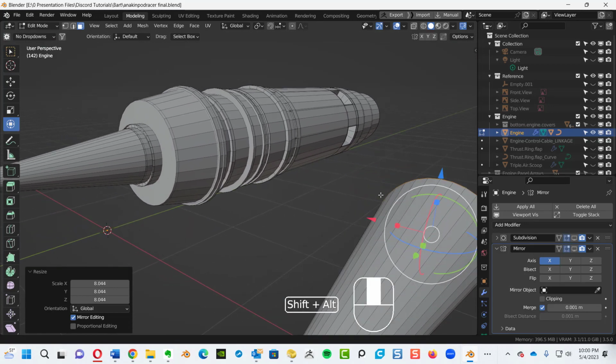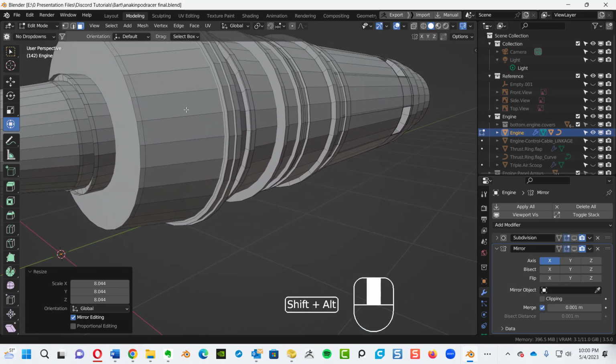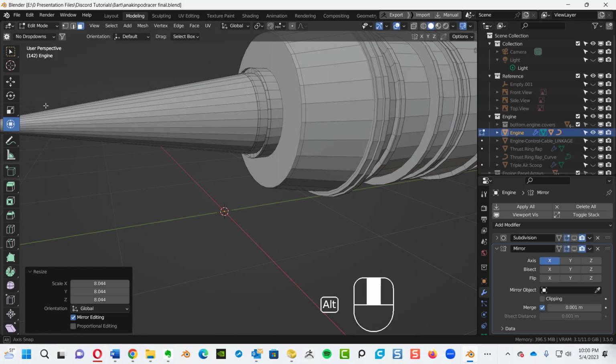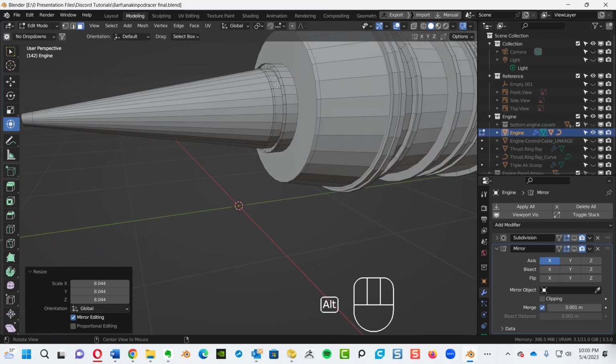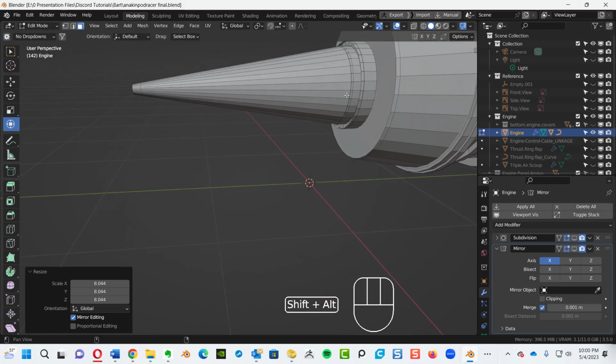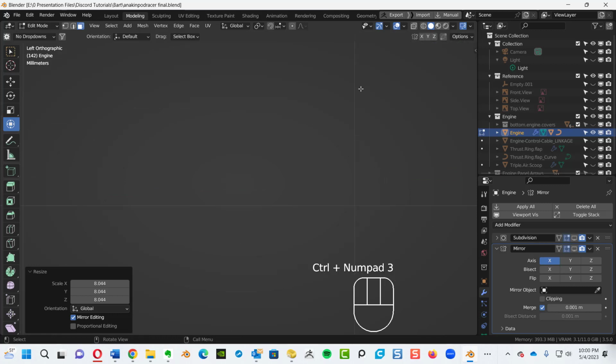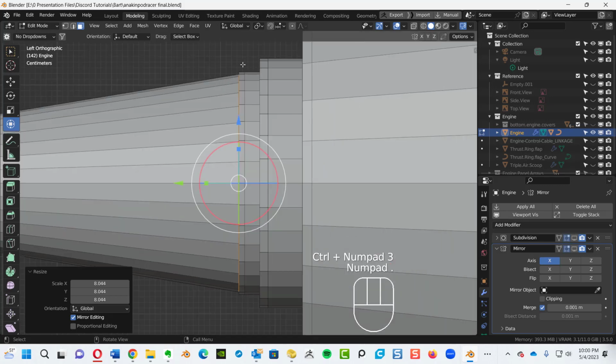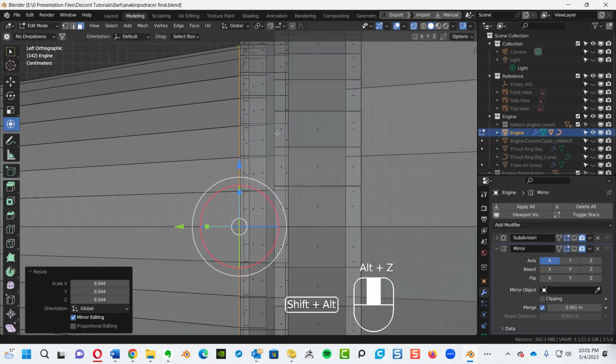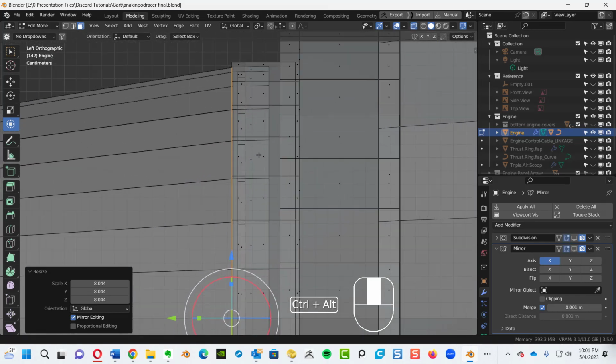It looks like you've got, let me take a look at, come over here. Yeah, it looks like it just goes straight on back. Now I'm going to extrude this straight on back, and it looks like from the side I'm going to be seeing 2 lines here. So if I come back, go to my side view, I want to bring this back to this second line. Alt, there we go.